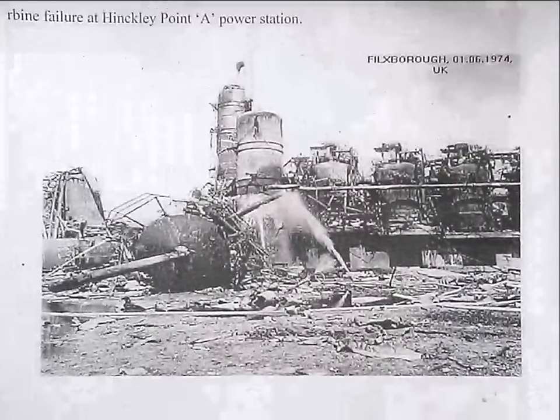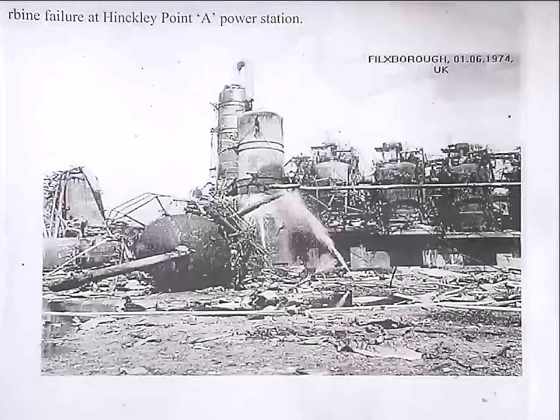There was a bypass pipe put in, and that then failed. And the leak of the raw component, the cyclohexane, into the plant caused a massive explosion and flattened a lot of the buildings in the structure. So you can have quite dramatic failures, and that isn't good news at all.